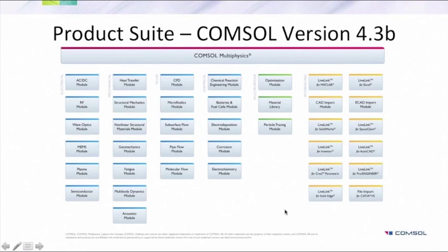Here, on the right side, you see all those different boxes with a yellow bar, and this shows which kind of CAD interfaces or different products we can have a live link with. With live link, you can actually stay in the product, perform a COMSOL analysis, be in the product which you are using, and alter it. The product, by the live link, will alter the COMSOL model, which can then be solved, and you can display the results in the product where you are working.